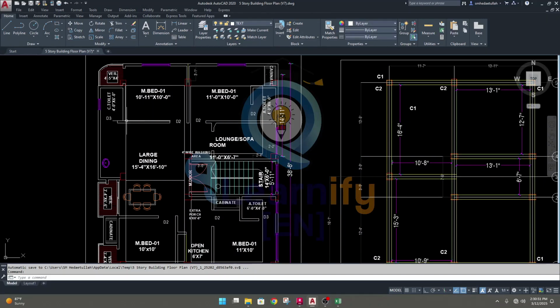So I will calculate this slab length and I'll find out its weight. After that I will provide this load as a floor load. I'll calculate total load, then I'll divide it by slab area, then I'll find out load per square feet actually as a slab area. Okay, so we'll go for it now.